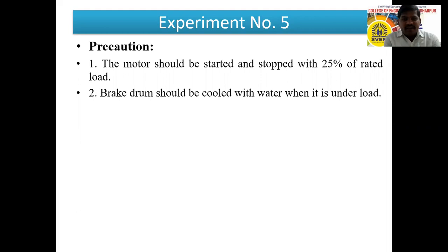Similarly, we have understood the application regarding that. We saw the application also. So generally a DC series motor can be used where some load is always present on the motor. In the condition where some load is present on the motor, we can use the machine. So generally I have also told that the DC series motor should never be started on belt connected load, or it should never be used where a belt connected load is there.